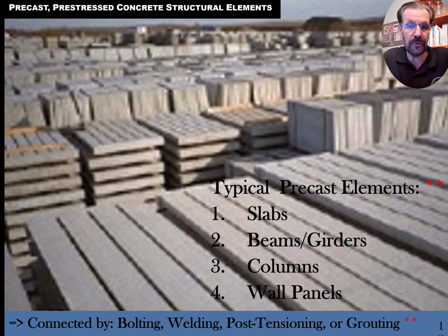So when you look at these flat slabs that are horizontal in this picture, those are floor or roof slabs, whereas these panels that are vertical are generally wall slabs. They will generally store them vertically because they don't tend to make them strong enough to be held horizontally. They could be, but maybe not. So that's another trick that can tell you whether it's a floor slab or a wall panel. In this category of slabs, there's something called a double T and a single T that are sometimes in the category of slabs, but they can also be beams and girders. So some cross over the line between the two, blurring the definitions here.